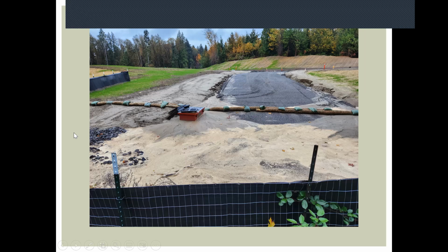We got our first big rain overnight last night. In my neighborhood, I think we got just over an inch, probably in 10 or 12 hours. And this is what happened. So I do want to note that their sediment controls are working. The sediment controls are doing what they're supposed to do. But we're not regulated on sediment in our state. We're regulated on turbidity. There is a catch basin somewhere under this muck. I don't remember exactly where it is, but it's covered up.